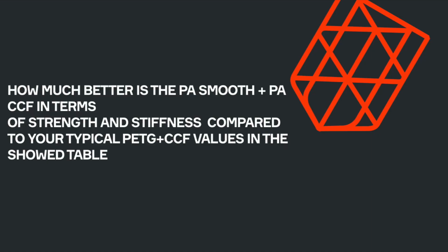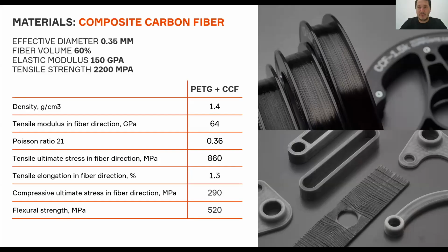How much better is the PA smooth plus PA CFC in terms of strength and stiffness compared to your typical PETG values? It's not different. So all the properties are, as per the rule of mixtures, mostly defined by the fiber.